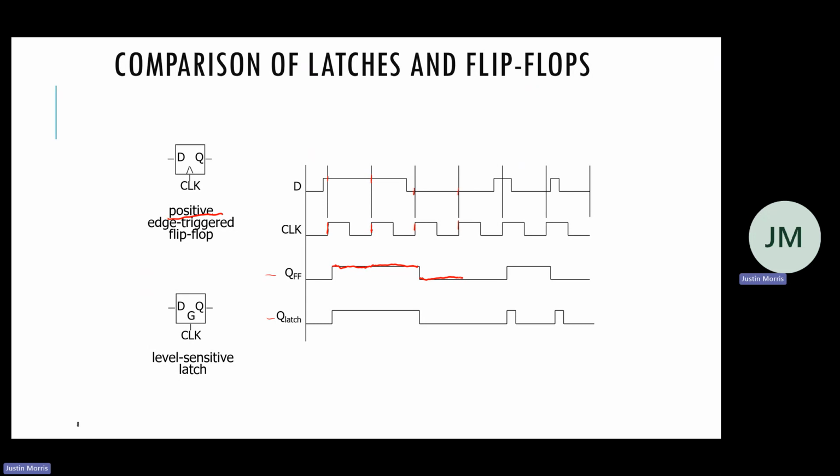So for a full clock cycle, it was 0. And then positive edge here. We sample it again, and it's 1 this time. So we hold 1 for a clock cycle. Positive edge, it's 0, so we switch to 0 for one full clock cycle. Okay, so that's the D flip-flop.